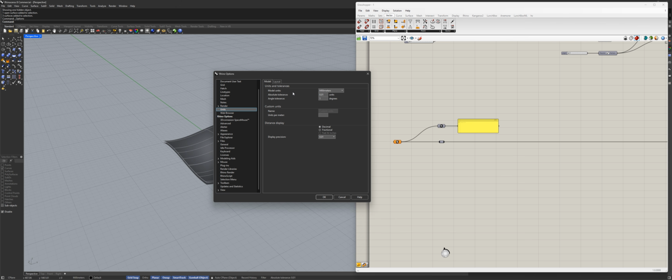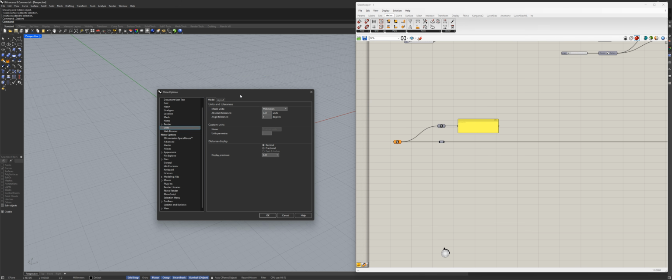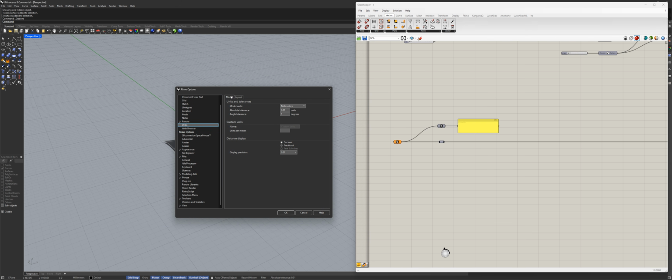It's much simpler in this regard and has only a few parameters. So absolute tolerance is your position, angle tolerance is your angle deviation, right? So the parameters of the documents are important because Grasshopper inherits what Rhino has. So whatever tolerances you have, the Grasshopper will follow, right?